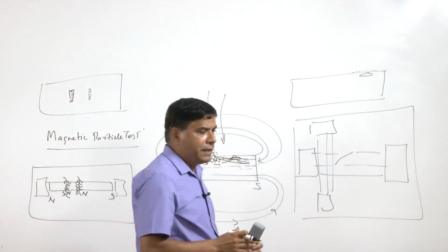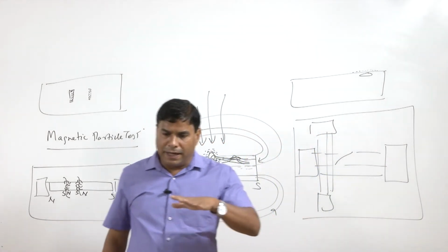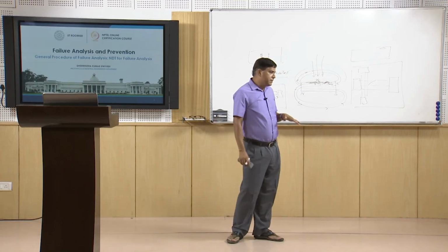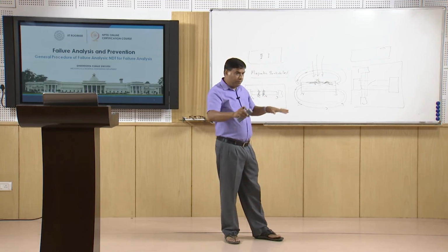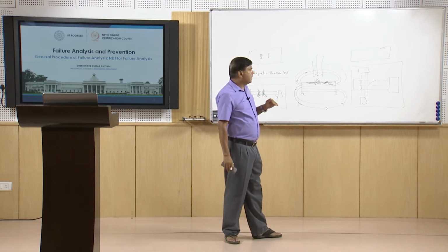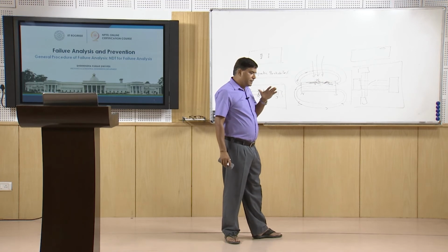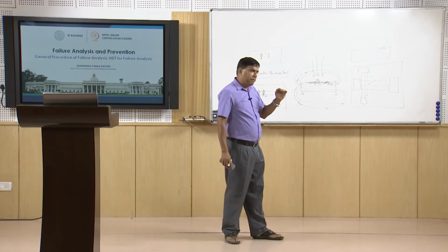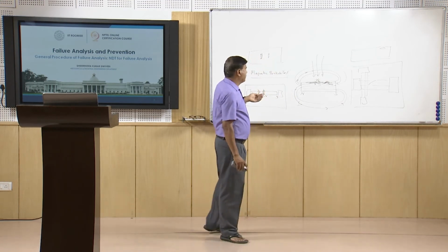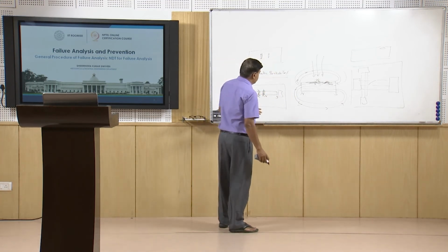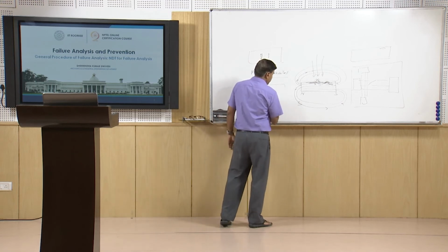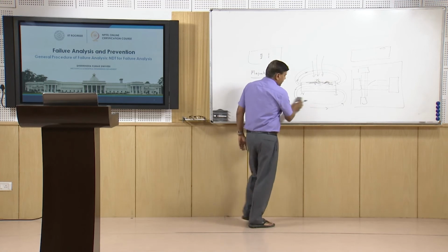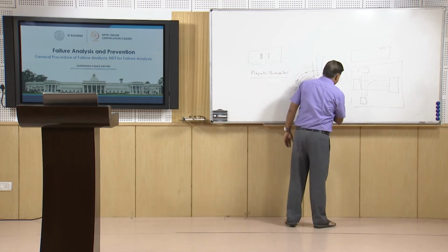That will indicate the location and the shape of the discontinuity under the surface. So, very weak piling up of the powder particles will take place when the discontinuities occur below the surface in the case of magnetic particle tests.